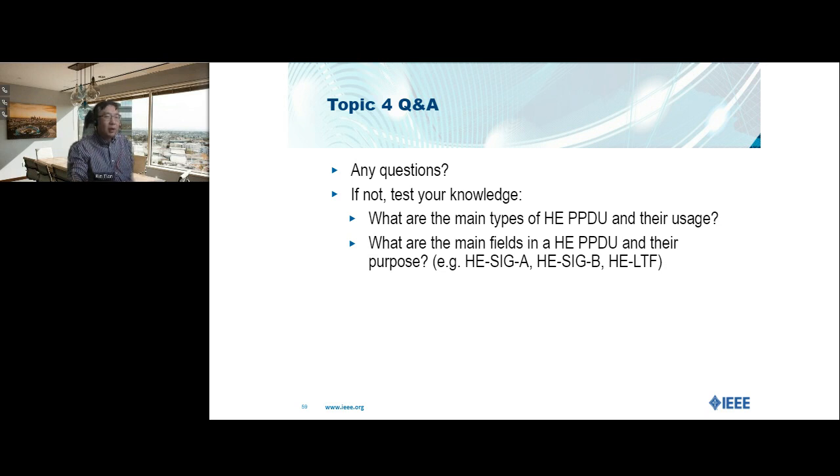Okay, in which condition do you have 0 GI for the guard interval? Okay, we don't have 0 GI. There are 2 meanings here, and I want to be clear what we are saying. I understand your question, 0 GI mostly represents saying there is no GI. No GI doesn't work for OFDM because, to ensure orthogonality of OFDM transmission, you need to add the GI to ensure the delay spread doesn't get into the next symbol. So GI is always needed.